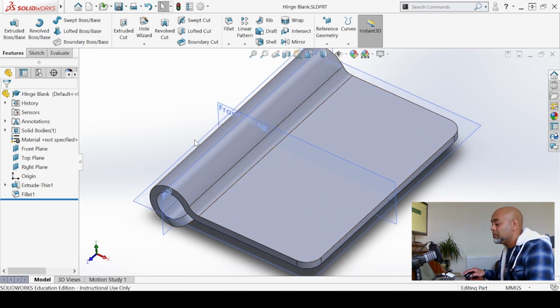At this point in time, I would like to come up with 4 holes, so probably one round there, another one round there. I want to spread them out like this just to constrain the hinge quite uniformly. You don't want the holes lying here because then you're going to have a slight lift off. You don't want that. So you want it to be constrained quite nicely. So probably 2 round here and 2 round there.